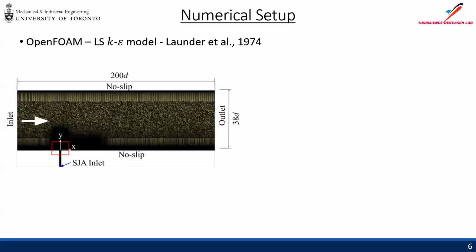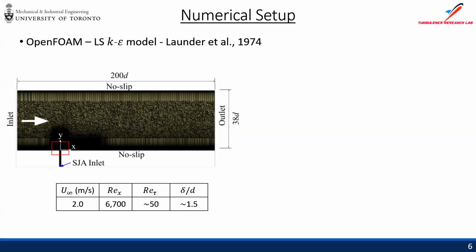We're not very satisfied with URANS results for that, and therefore we've decided to go with a duct crossflow instead. However, to ensure it's still comparable with the experimental flow, we gave it a very short development length, resulting in a very thin boundary layer. We're talking several millimeters, similar to what you expect on an airfoil right before separation.